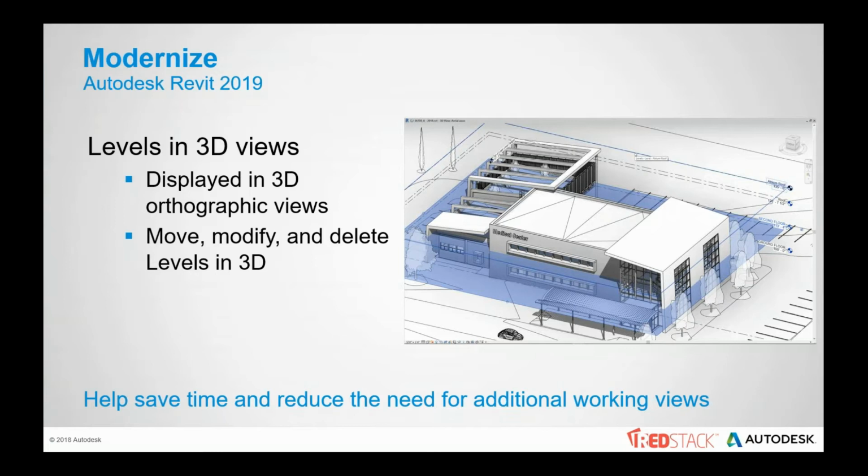When it comes to levels in 3D views, levels are perhaps the most important Revit datum element as they establish any important vertical location within a project. When working in a 3D view, you can now display and edit levels in orthographic and perspective 3D views. If levels are not displayed in 3D, you can easily turn them on using the annotation tab of the visibility graphics override dialog for the active view. With the 3D view selected, you can enable or disable its annotation, modify its parameters like height and name, and even resize its extents using the grip handles at the edges.